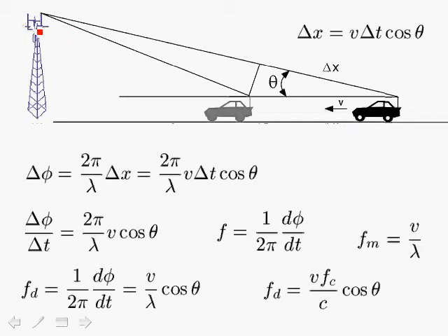Here we show the base station transmitting a signal to a mobile. The base station transmits at a carrier frequency f sub c, and as the vehicle moves, the received signal at the antenna from the transmitter exhibits a phase shift as a function of time, and we will show this. For example, when the vehicle is in this position here, the distance from the base station antenna to the vehicle antenna is shown here. When the vehicle moves, the distance becomes smaller when it moves toward the base station, and we have a phase shift between the vehicle at this position and as it moves.